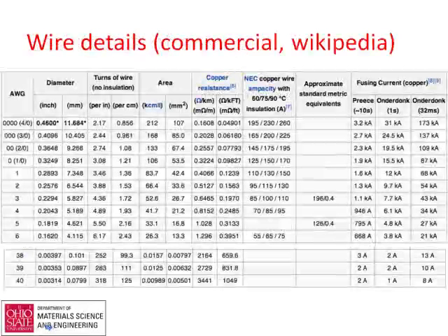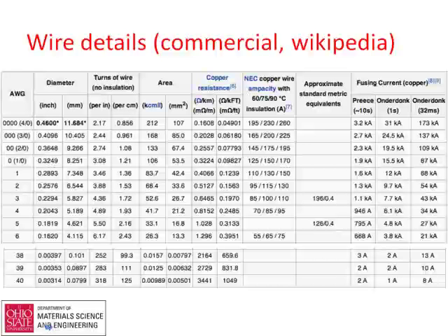So again, commercially, people have thought this through tremendously. And there's this thing called American wire gauge. The higher the American wire gauge is, the finer the cross section is. So at the bottom of it is zero gauge. A zero gauge wire is 0.3 inch diameter. You don't want to get hit with that, and that is something that you might end up carrying.